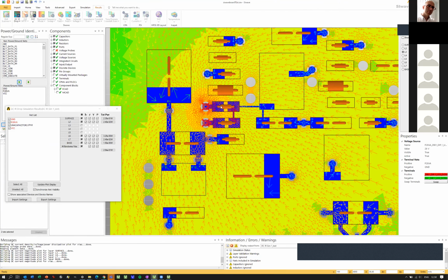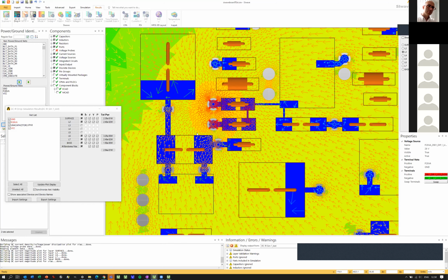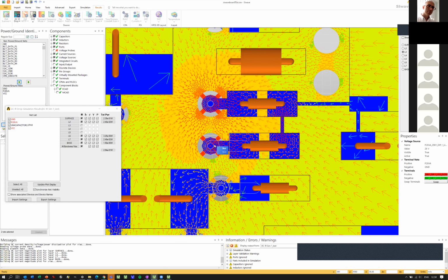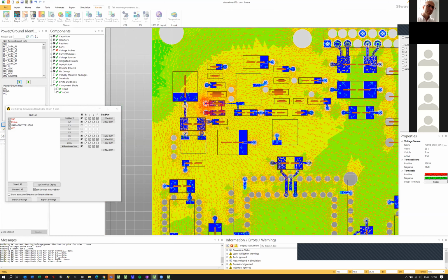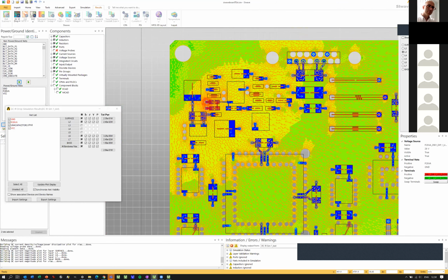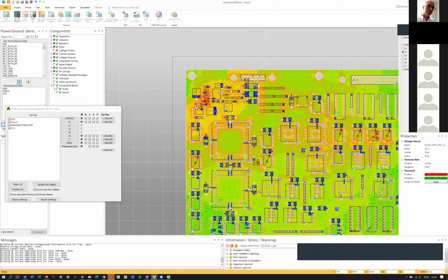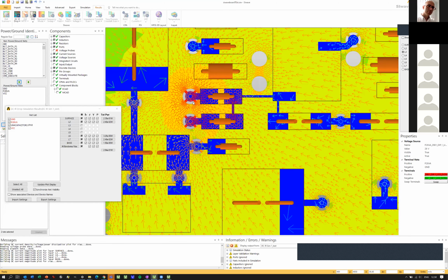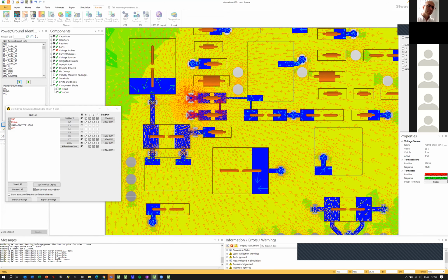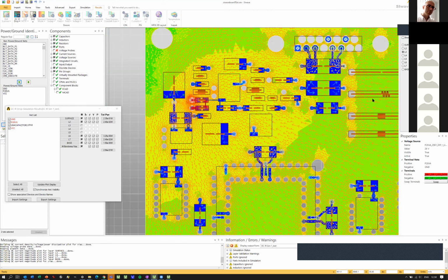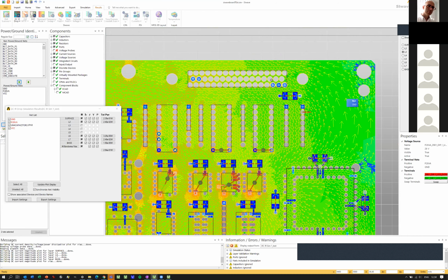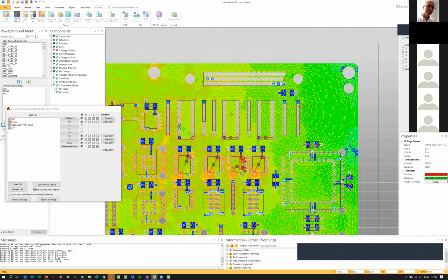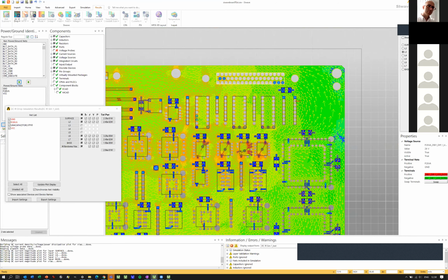And for example, here we can see that these two vias are draining a lot of current because these are most of the power supply vias, and we can also see that those are pretty heavy, so lots of current goes through that. We can see that here nothing really happens, so the current has always a loop. Current will travel back, it will go through.